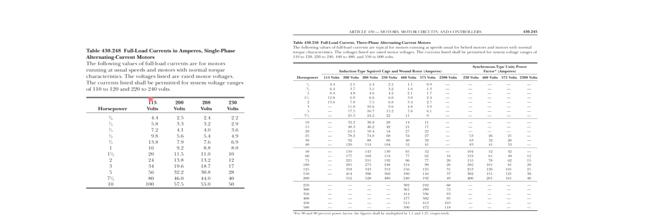Some people call it 120 volts. You use the 115. And then 220 to 240, that's why they give you the 230. Kind of go back and forth. So if you see something 220 or 240, you go to 230, use this column. 110 to 120, you use the 115 volts.